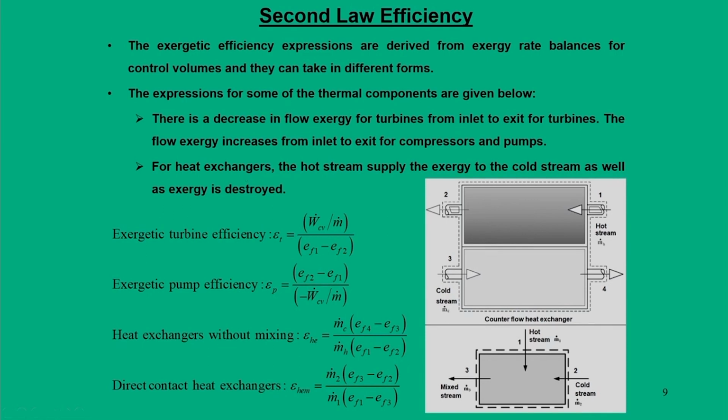In fact, heat is the source for which complete conversion is not possible. So, exergy calculation is very significant in terms of second law efficiency. Heat exchangers can be of two types. The first one is a counterflow type, in which there is a hot stream entering and leaving, conditions 1 and 2.